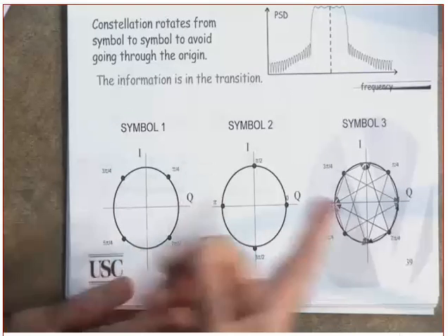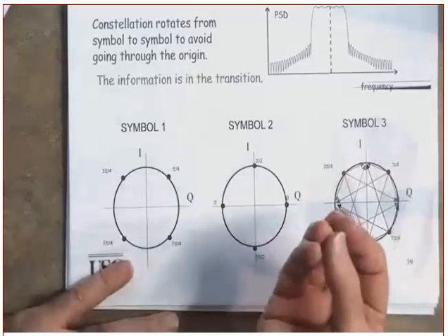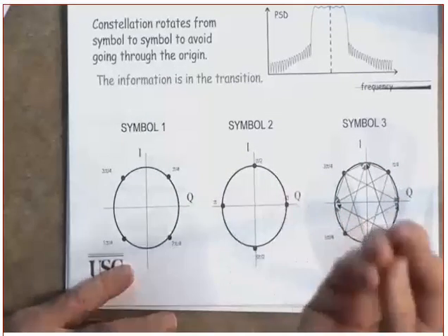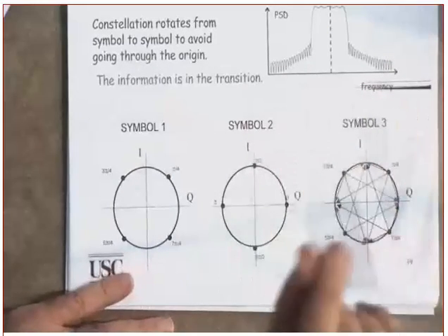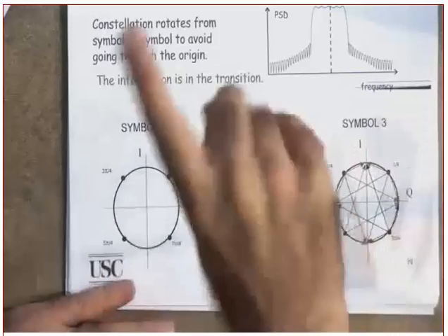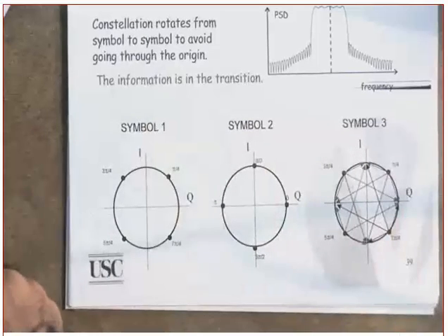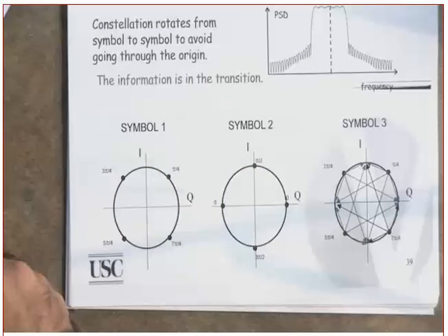No, you didn't get it. Is this 8 PSK? It's not 8 PSK. If it was 8 PSK, every symbol represents how many bits? 3 bits. And all the signal points are from the same constellation. In here we alternate between 2 constellations. Clear? Help me. Why? Let's see if you can tell me why.